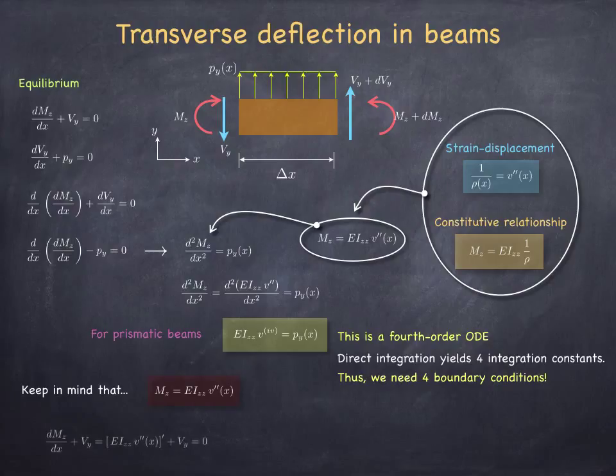And since we know that the derivative of the moment plus the transverse shear force, the internal force, is equal to 0 at all locations, that's the moment equilibrium equation, we can then rewrite that expression as follows. And again, for prismatic beams, the derivative of EI is 0, so that comes out of the bracket, and that tells us simply that the internal shear force is the third derivative of the transverse deflection field that we have solved from the fourth order ODE, times minus the bending stiffness.